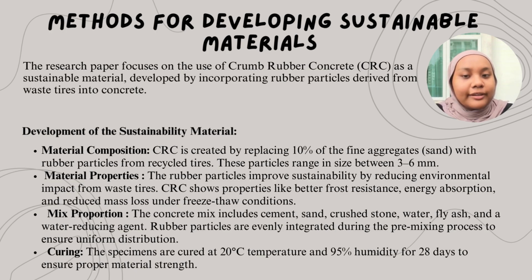The first one, material composition. CRC is created by replacing 10% of the fine aggregate sand with rubber particles from recycled tires. These particles range in size between 3 to 6 mm. Number two, material properties. The rubber particles improve sustainability by reducing environmental impact from waste tires.